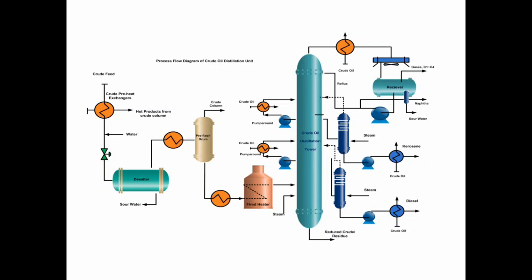And suppose we are getting 50% residue, we cannot just throw it away like that, because the economy of the company will suffer a loss. But here we cannot heat it further as well. So we cannot throw the residue away, and we cannot heat the residue either. So to process RCO, this reduced crude oil residue, we take it into the VDU, that is the vacuum distillation unit.